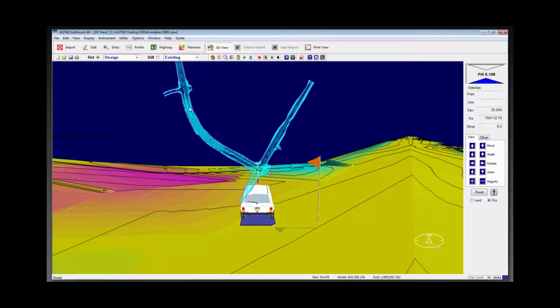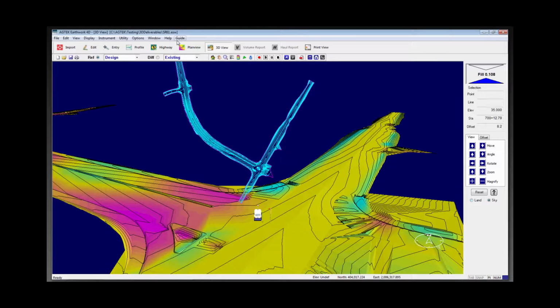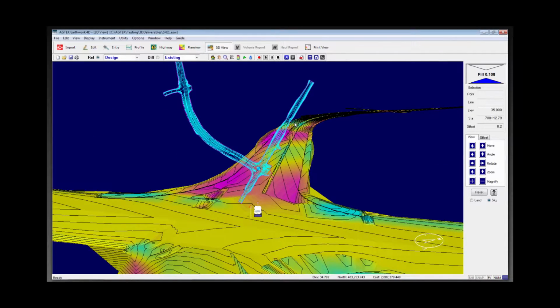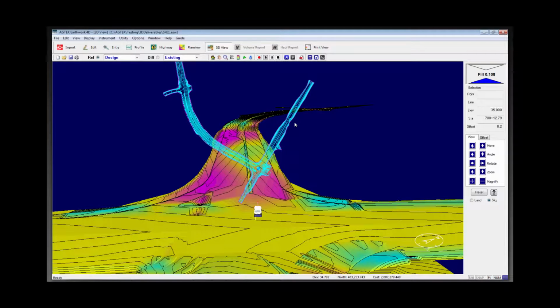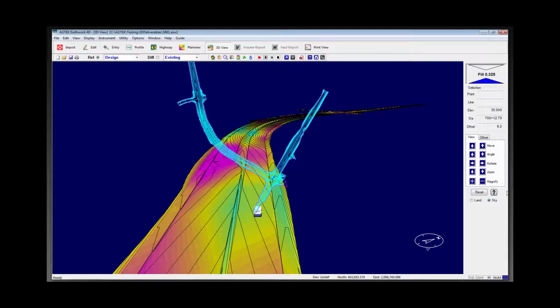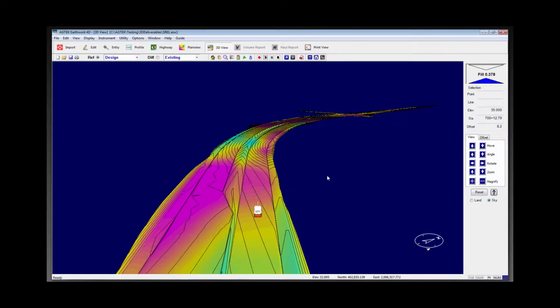Now there is some help here, but you have a way to move around over here with this thing. The hotkey that's important is this B. It rotates you to a sky view type thing where you can actually drive. And then you can use your arrow keys to kind of move around this view. And so if you want to drive this vehicle up this roadway and just kind of analyze it, you can go like this, just hit the up arrow key, or you can navigate with these, obviously these manipulator buttons over here. And if you don't want to see that overview, you can just hit the O key and it will turn that off, and then you can kind of drive along it a little closer here.